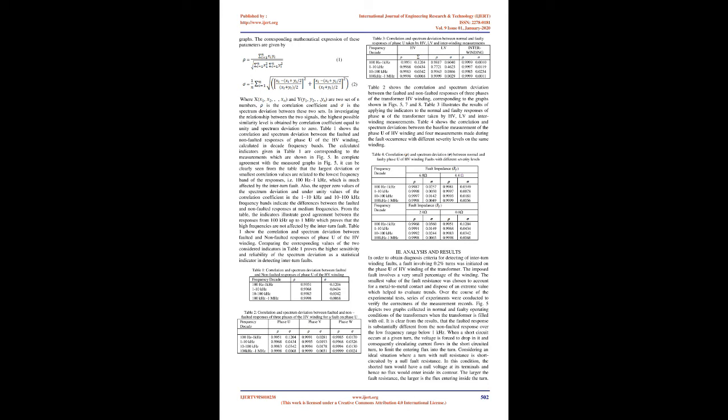The sketch in Fig. 3 illustrates an exaggerated presentation of the corresponding geometrical and circuit domain of the transformer coils and also the details of the tapping points and the initiated fault on phase U of the transformer HV winding. In the figure, the external limiting fault resistance and the time-controlled switch for initiating the fault are denoted by S and RF symbols respectively. Fig. 3: exaggerated transformer coils and the initiated fault on the second disc of the HV winding on phase U.